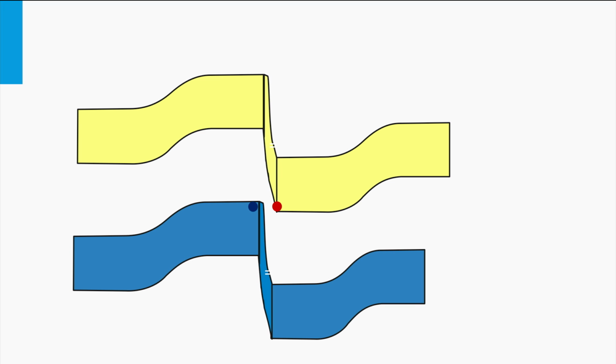The creation of such reverse junction can be prevented by the inclusion of a so-called tunnel junction. It provides a low electrical resistance and has a high bandgap to prevent any parasitic absorption losses. The high bandgap tunnel junction is relatively thin. It means that the valence band at one side is lined up with the conduction band at the other side of the tunnel junction. The depletion zone of such junction is extremely narrow. As a result, the slope of the valence band and conduction band are so steep that the electrons from the N layer tunnel through the small barrier to the P layer, where they recombine with the holes.